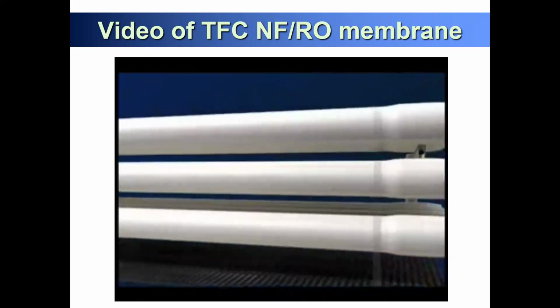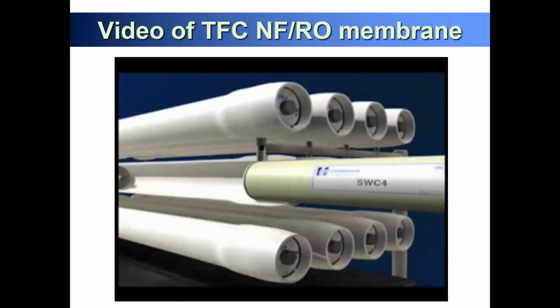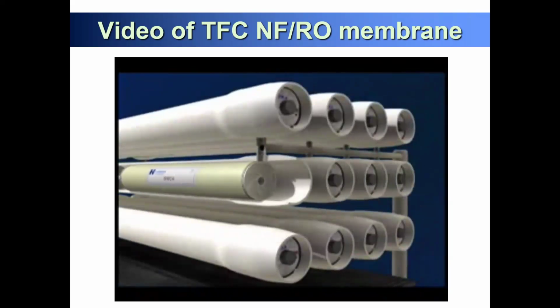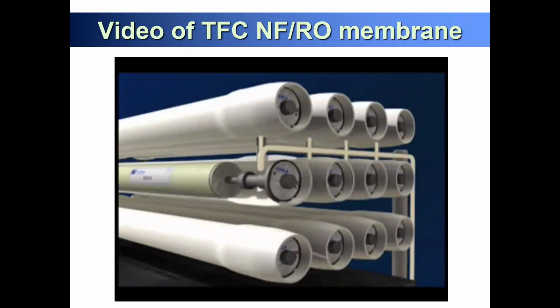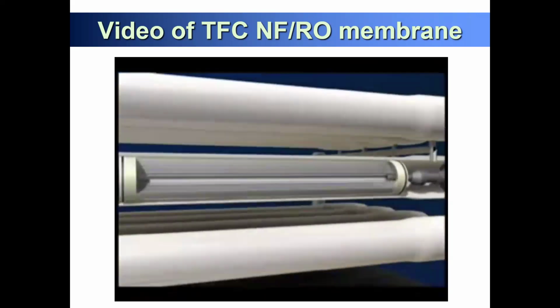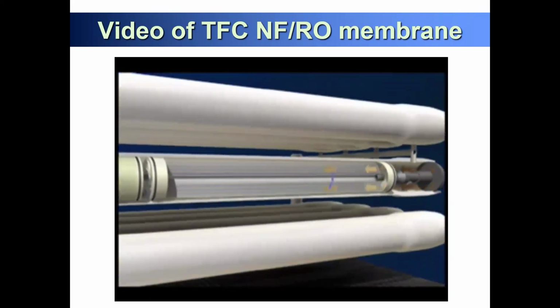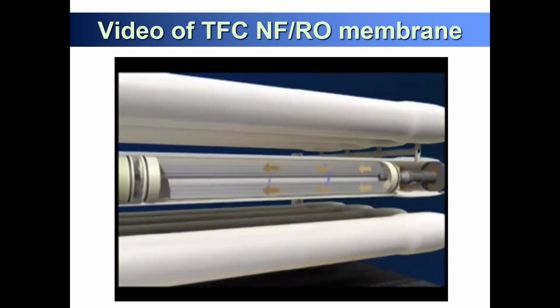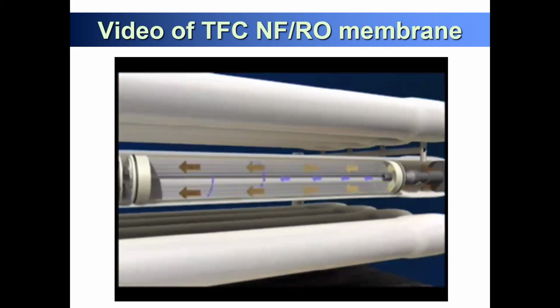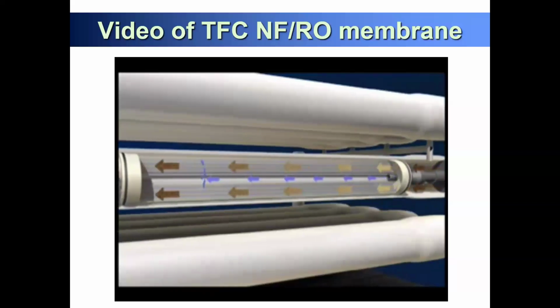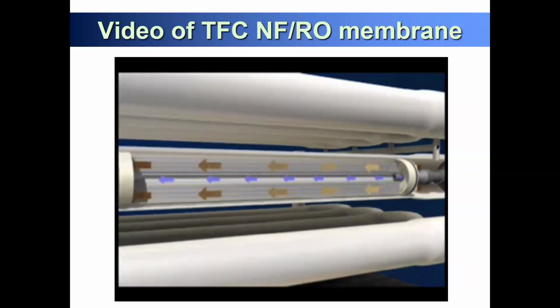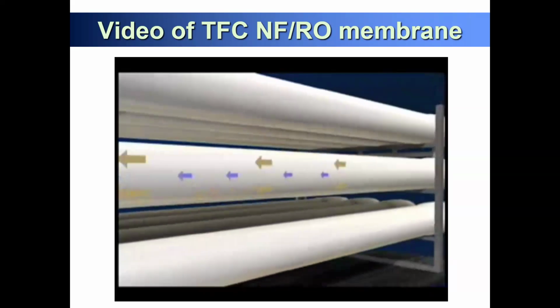Hydronautic spiral wound elements can then be loaded into pressure vessels and interconnected with additional elements to complete any number of design specifications. Once the end adapter is connected to the last element and the pressure vessel is sealed, feed water can be introduced and then treated. The feed water that does not permeate through the membrane becomes enriched in salts as it travels through the feed channel spacer due to permeate water being removed.